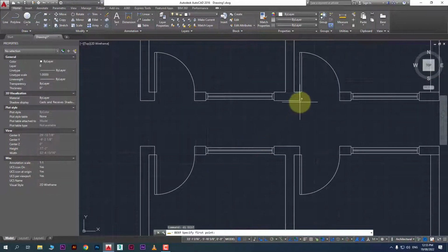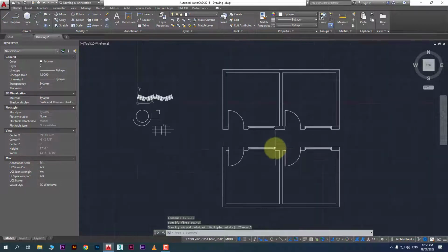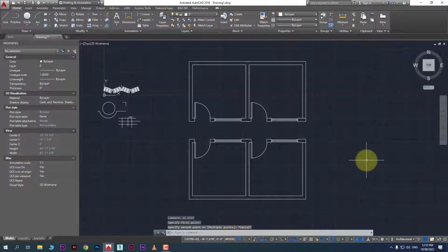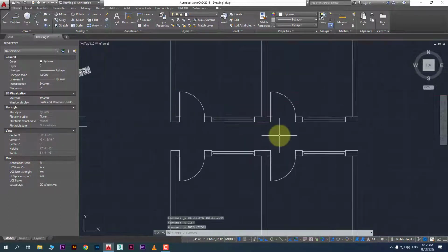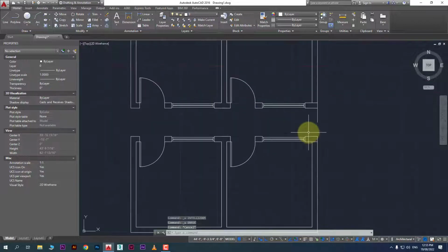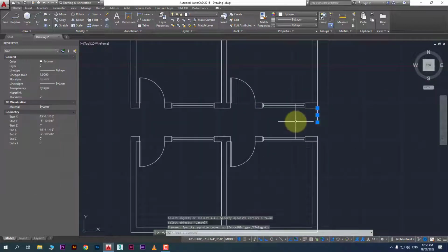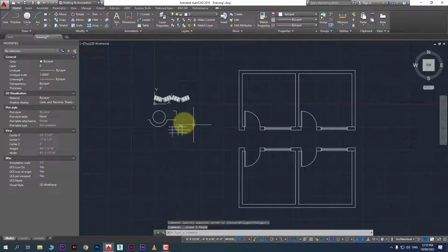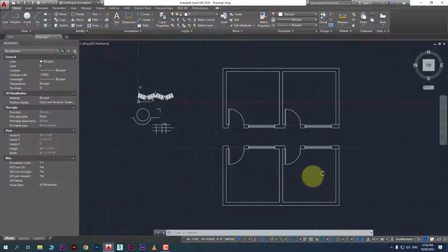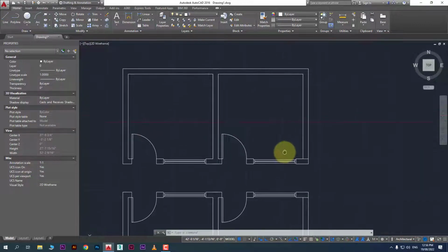For distance you want to vary, just check. So you have 4 feet, right? So by using this mirror command, like if you have created only one, you can create many. All right, and copy we have used also, so you can use this all. Okay, so this is like we have move, rotate, copy, mirror command. Okay, and trim and extend. Let's finish also the other command. We have only stretch and scale left behind. So let's finish. Then you can also create the whole plan.